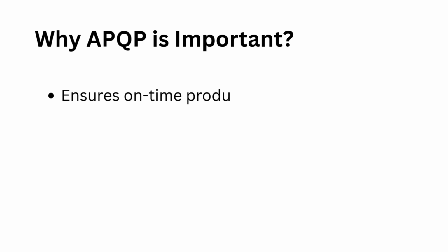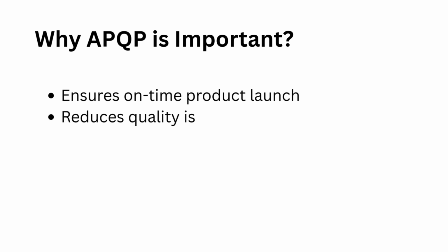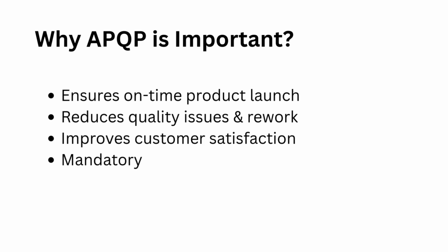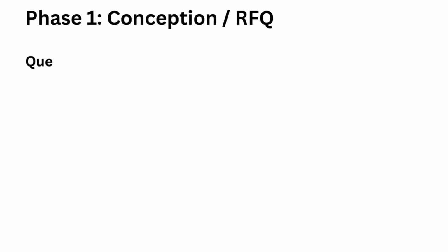Why APQP is important: ensures on-time product launch, reduces quality issues and rework, improves customer satisfaction, mandatory for OEM and Tier 1 suppliers. 5 phases of APQP. Phase 1 of APQP is called conception or RFQ phase.